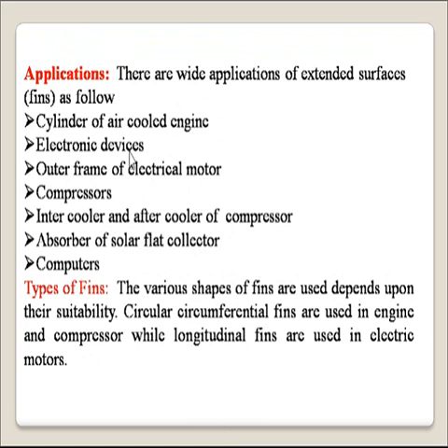There are wide variety of applications of fins. Fins are used in air-cooled engine to cool the cylinder, and the circumferential fins are used in engine. Then fins are also used in electronic devices to dissipate heat generated in the chips or electronic device. Fins are used on an electric motor casing, which are longitudinal, to dissipate heat from the motor.